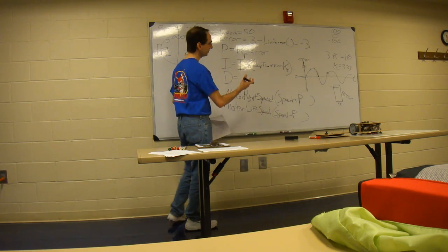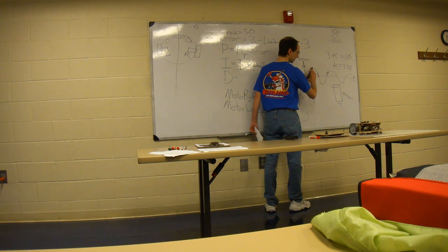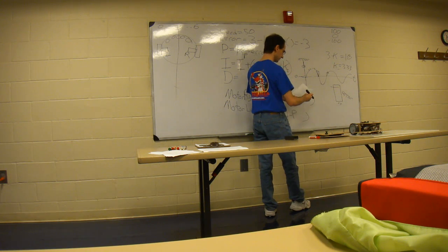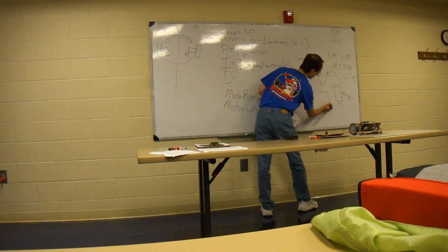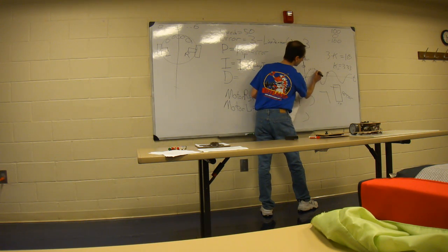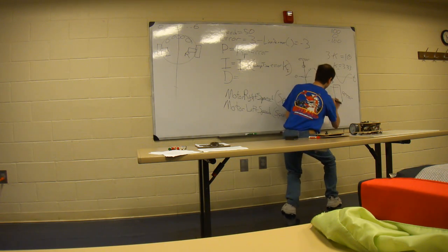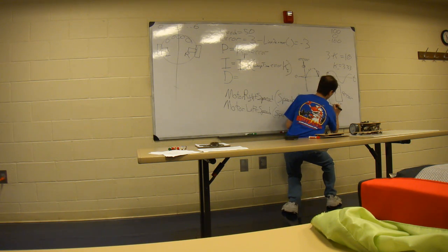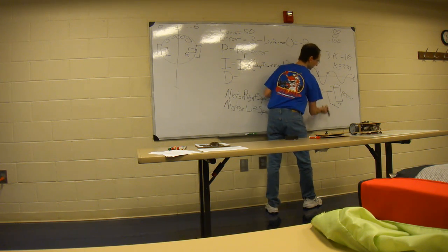So the D term, we calculate it just by calculating the velocity, which is just the slope, which is just rise over run. So the rise is just the difference in error of the 2 points. So we would have the error and the last error, and then the run is just our loop time again.